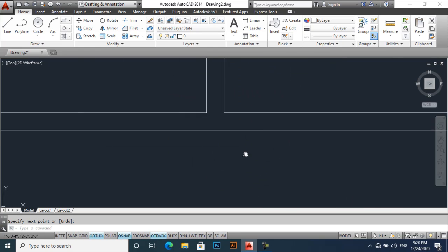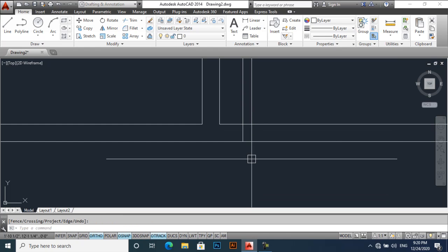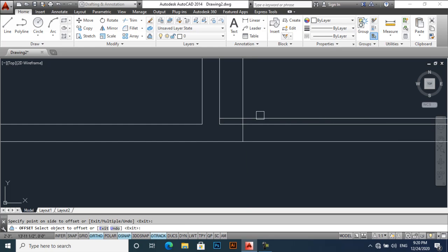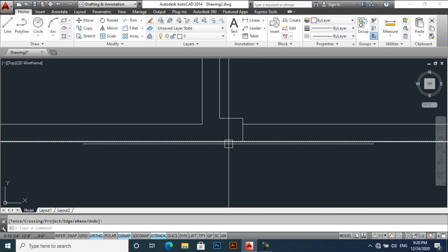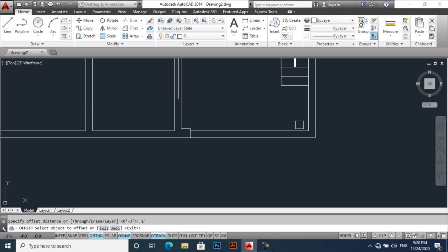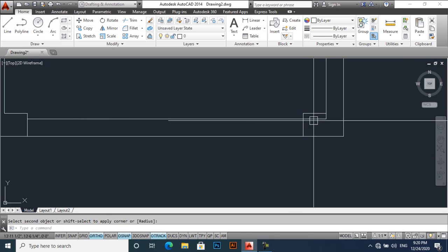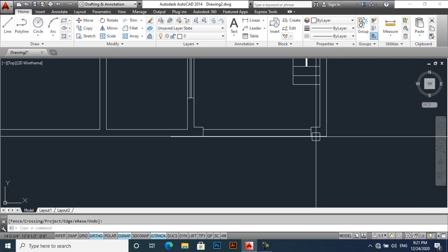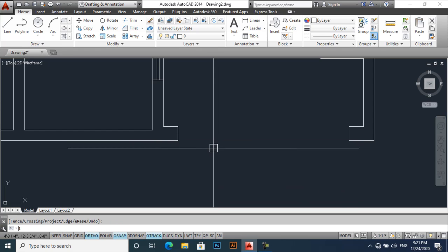Now let's take an offset of 1 feet, extend it, and then offset 3 inches will be enough, so it will become a rectangular column. Offset 1 feet again, and extend it, offset 3 inches, we'll trim it like this, and also trim it like this.